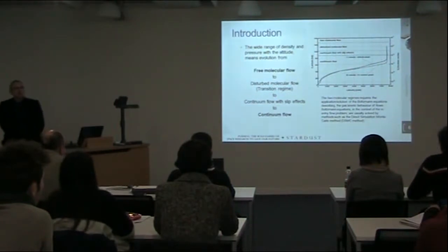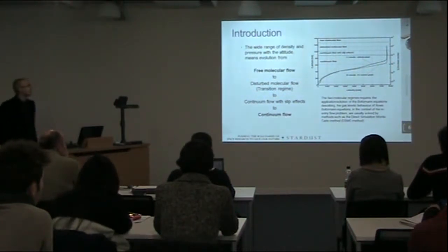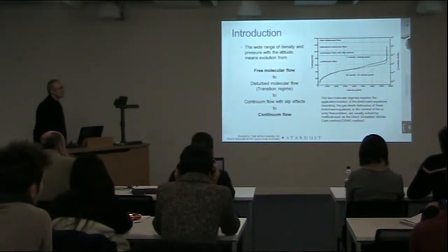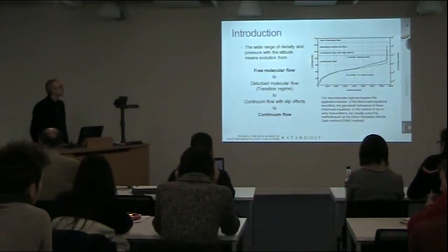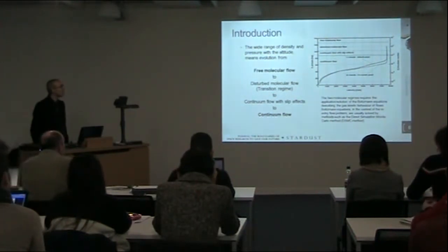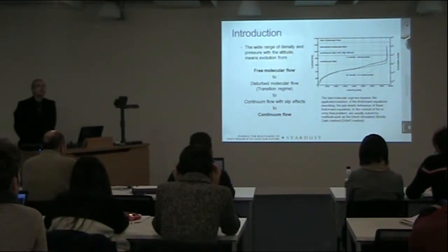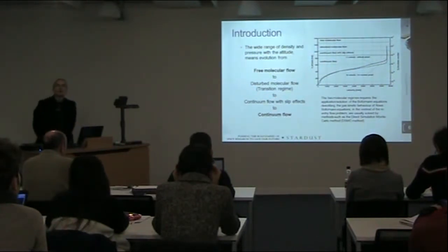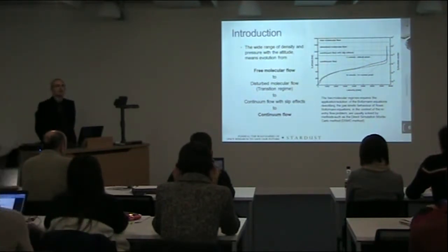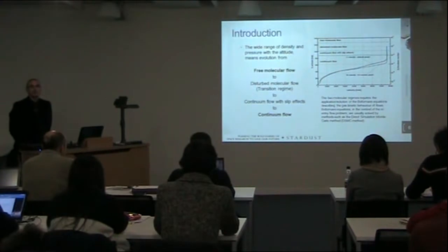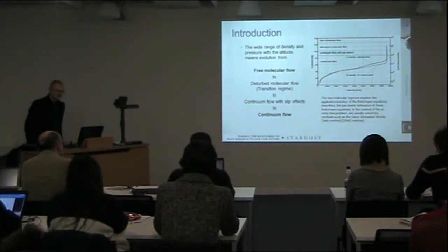In order to simulate the flow at the molecular regime, we cannot use the same techniques as for the continuum regime. We have to solve the Boltzmann equations, and this is done by direct numerical simulation. It could be molecular dynamics, or the direct simulation Monte Carlo method that I will describe later.